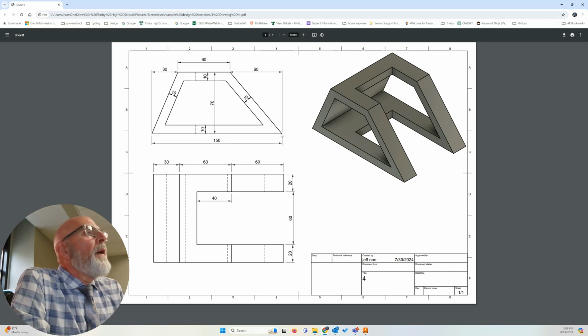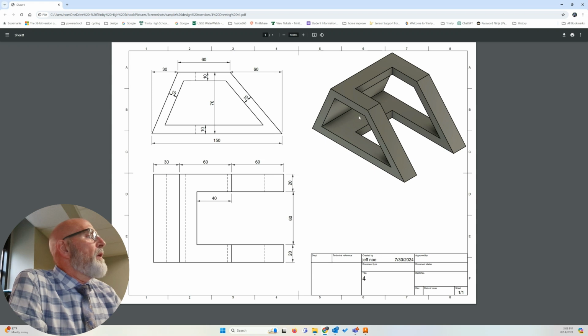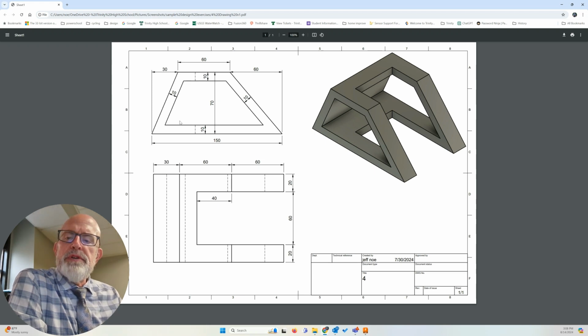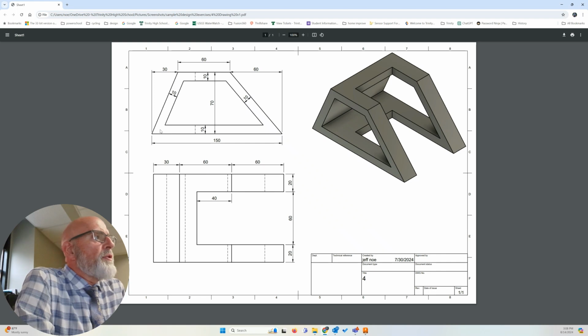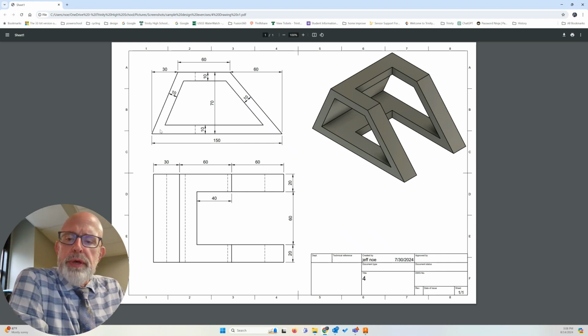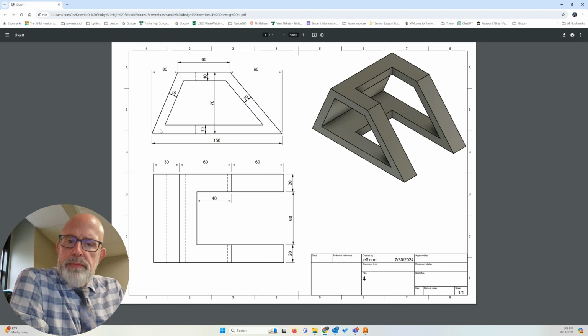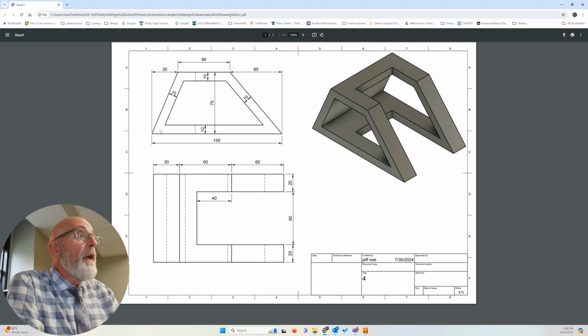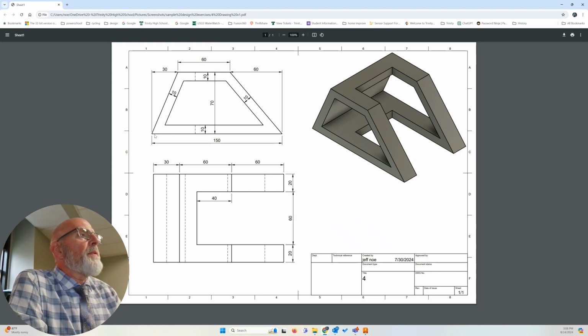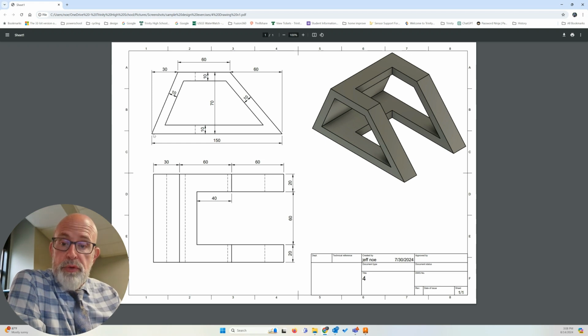Okay. I'm going to draw a couple of lines, but I'm going to change the format of them. I'm going to make them construction lines. Construction lines are tools that we use in designing that are informational in purpose. They're not actually part of our design. They don't represent a border or anything of that nature. They are just there for information. And I'm going to draw one up from the origin. It's going to be tied to the origin, so it'll be constrained to the origin.